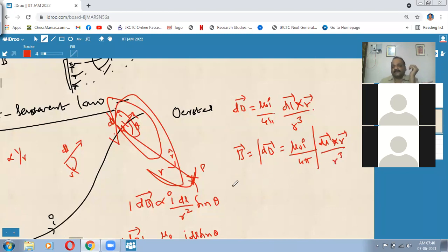Okay, with what you call that, it gives you the total magnetic field due to the entire wire. Now this is the Biot-Savart Law. So we can find out, for what amount of current in what type of wire, how much the magnetic field will be at so-and-so distance. Now we will get it out.